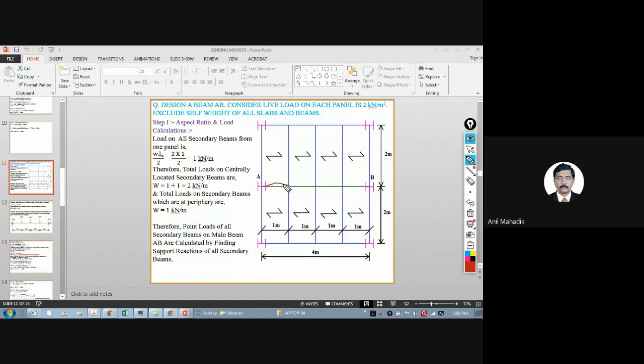For example, I'm just giving an example, so it will buckle. That means your main length is this 1 meter and not 4 meters. Try to understand. Getting? So your L will be 1 meter. Then for L effective, you will give some coefficient, let's say 0.85 L. So it will be 0.85 into 1, for example. So only in the L upon R calculations, you will take this L effective, which depends on the L, which is 1 meter. Have you got this?